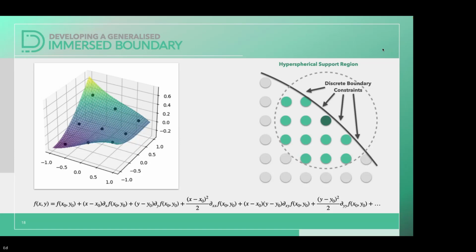We're also going to grab the boundary constraints at some discrete points on the boundary. They aren't drawn on here because it just makes it all too messy. The boundary in this sense isn't really continuous, because nothing is really continuous for finite difference. We pick some suitably positioned points on the surface to encapsulate its geometry, and we can use these to fit our function.